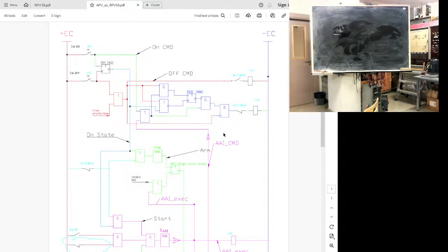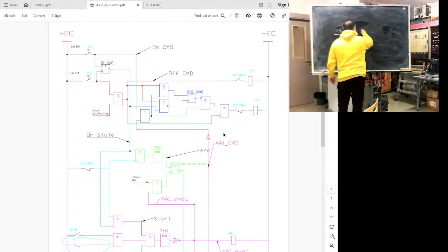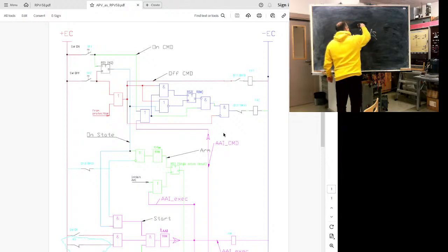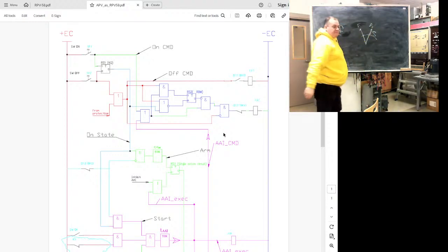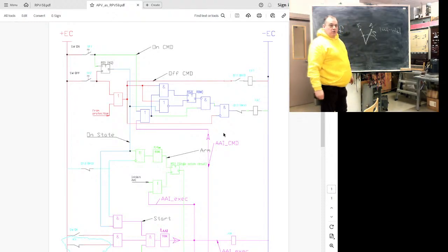This can be done only within a limited range of slides. We need to perform simulation and be sure that the resulting system will be stable, or otherwise we will destroy everything. So reclosing can be performed only within a limited range of delta angles. It's not enough. The frequency difference should also be within limit.